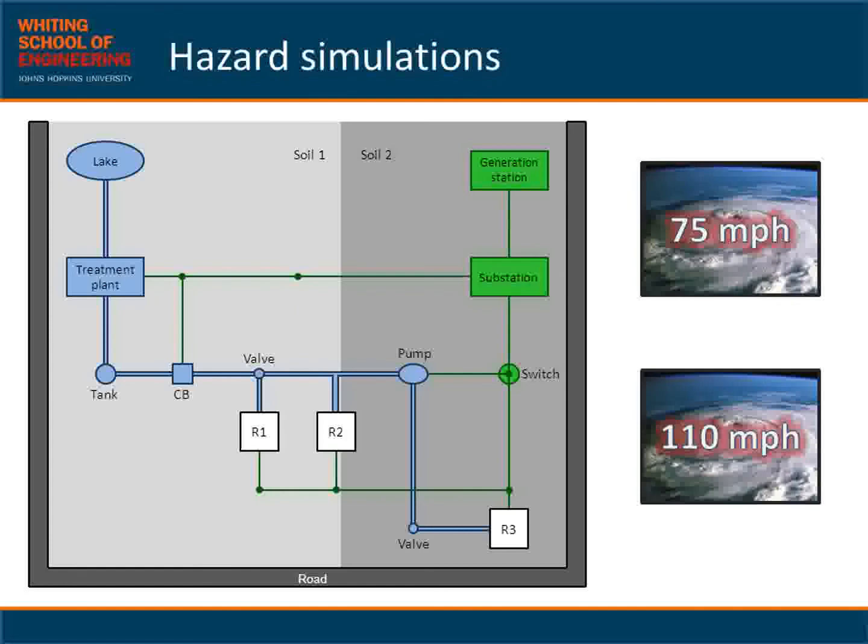For a given storm, we assigned each network element a failure state, with probability from the associated fragility curve. If a network element relied on more than one component for operation, such as pole foundation and pole material, the element was designated as failed if one or more of its components failed. After the failure state of each network element was initially calculated, failures were propagated through the network based on dependency matrices created from the mirror web.